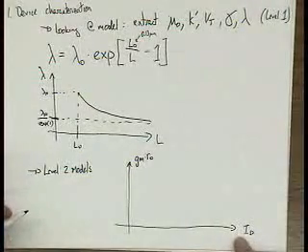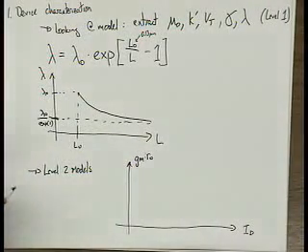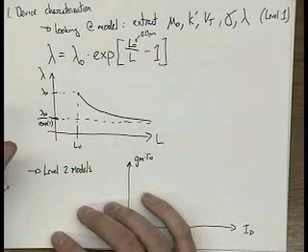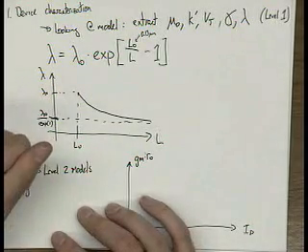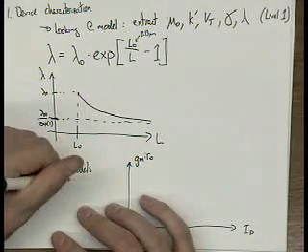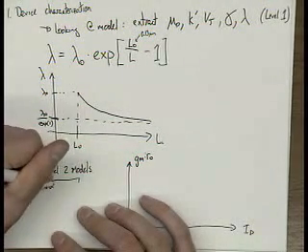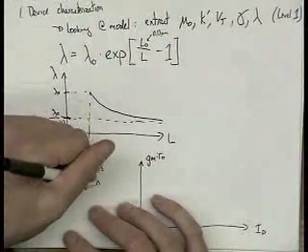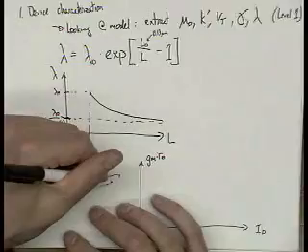That's the only thing you're changing. If we assume the square law model, level 1, gm in terms of ID is equal to the square root of 2 k prime W over L times ID. So gm is proportional to root ID.